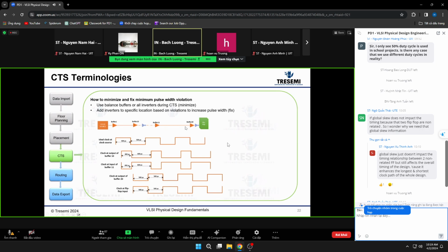Then eventually by the time you get to 20, it'll be 500 again. So 600 becomes 500, and then you invert the signal back. Then you have the original clock signal that you started with. So that's one of the ways that you strategically place buffers in to fix the pulse width.